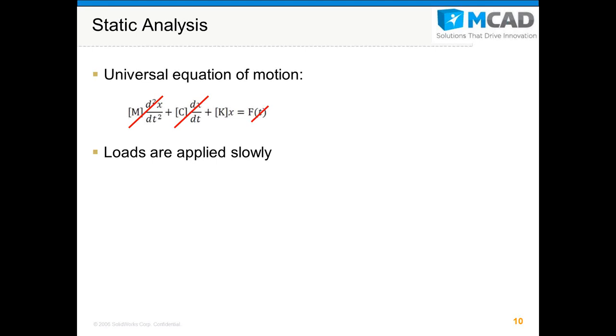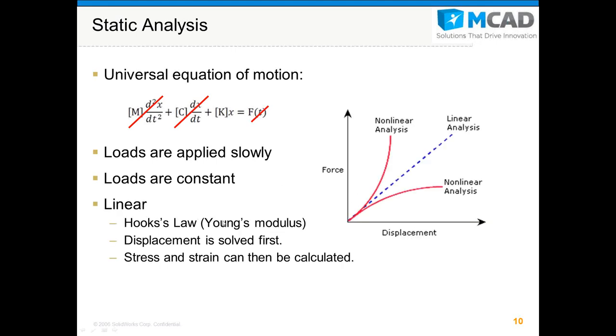Also, something to keep in mind with static analysis is that loads are applied slowly. They're not forceful. Remember, time is not really a factor here. So loads are applied slowly and allowed to converge. Loads are also constant. It's also linear, and what I mean by linear is the force and the displacement are based on a material curve that is linear.